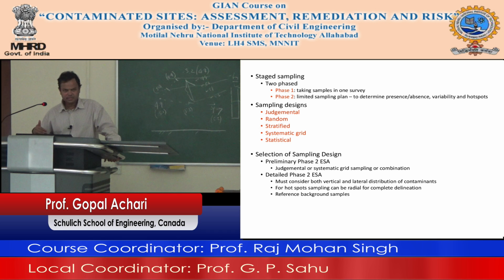Confirmatory sampling is I want to confirm something is present or not. If you mix it, it'll average out, and then you will think it's not there, right? Because in confirmation you are trying to confirm something is happening or not. But if you dilute it out with some other samples, it'll go away, right? Sampling from soil piles is needed to ensure proper depth representation. Randomized samples with sampling from hotspots.